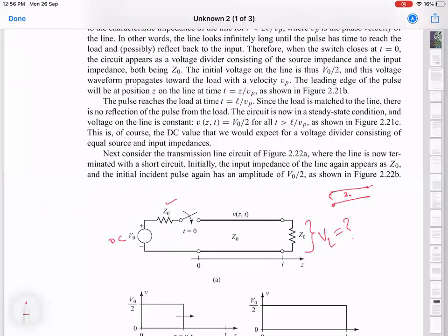That's one way of thinking about it, I guess, that because omega is zero, effectively the electrical length is zero. Because the thing is, you cannot really define electrical length for a DC signal. Then what does the physical length mean? It's zero for all physical lengths, right? Because the time available to you is infinite, because it's 1 over omega.